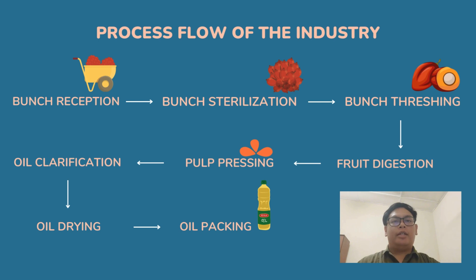Palm oil clarification is a crucial step in the palm oil production process, as it removes various contaminants such as water, fiber, and other solids from extracted crude palm oil, resulting in a cleaner and more marketable product. The dilution creates a barrier that causes heavy solid particles to sink to the bottom of the container, while lighter oil droplets float and pass through the water mixture under the influence of heat to break up the emulsion.